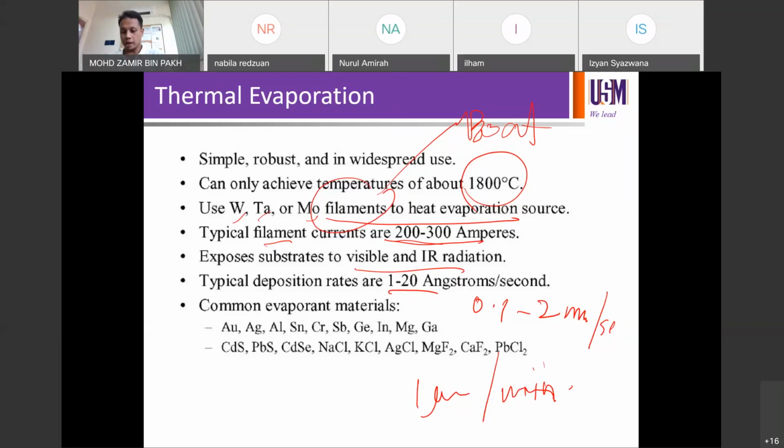1 micron divided by 60 seconds. So that's like 0.016 micron times 1000. So 16 nanometer per second, right? Slightly higher than this, 17 nanometer per second. So that's considered high. Even a system at 500 nanometer per minute is considered high already.